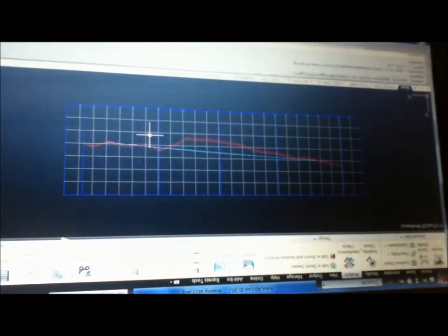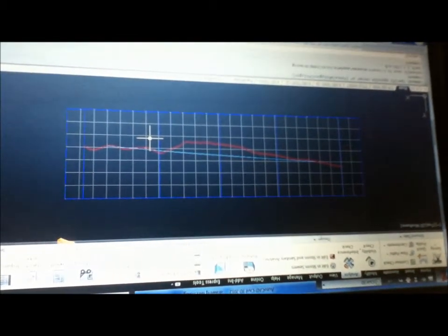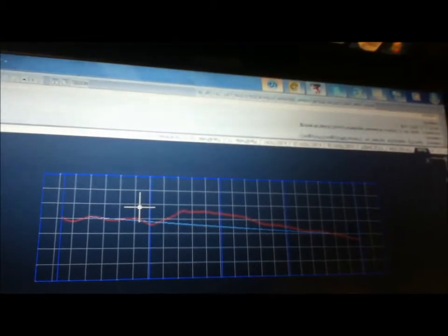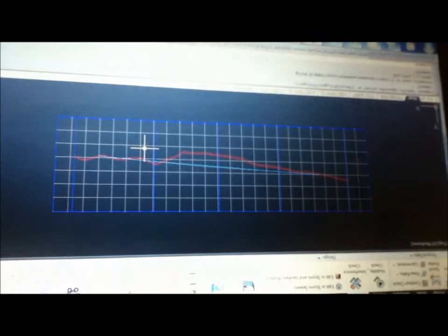And most of the time the center line of the culvert is perpendicular to the center line of the highway, but in certain cases this criterion isn't met, and that's when we have to indicate the skew number, which is obtained by measuring clockwise to the nearest 5 degrees the angle between the back tangent center line of the highway and the center line of the culvert. There are other criteria that come into designing and constructing culverts, such as the size.